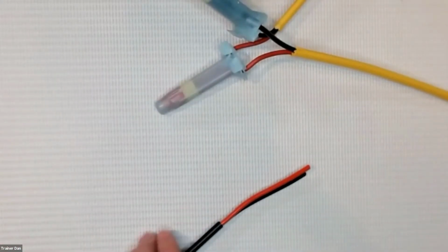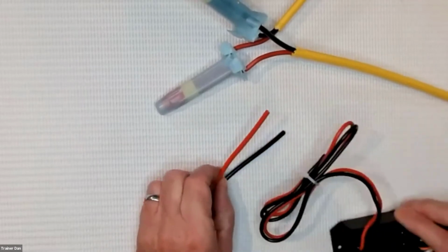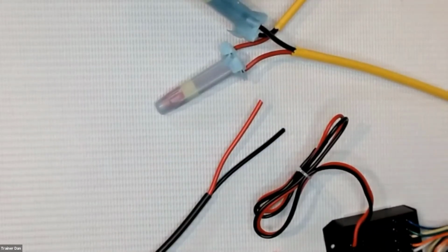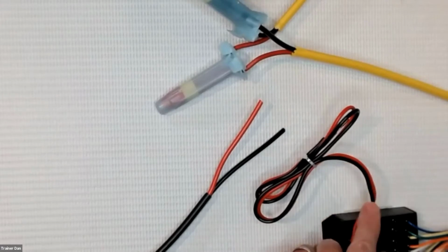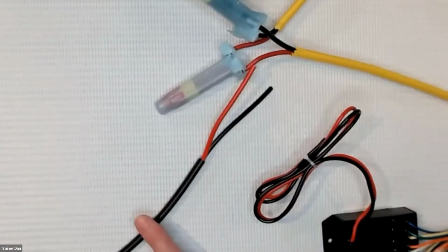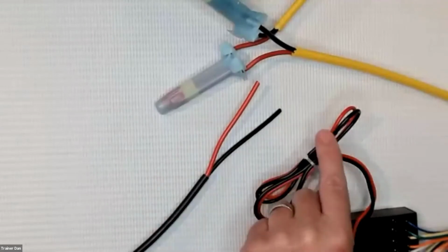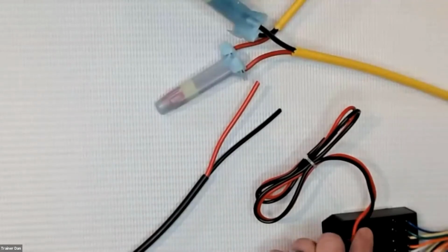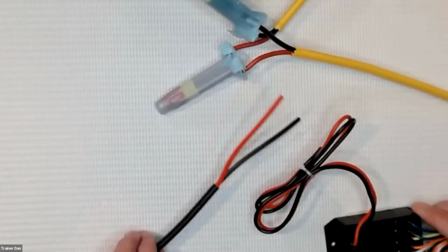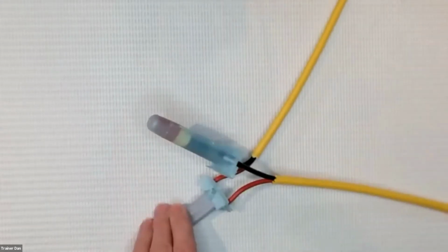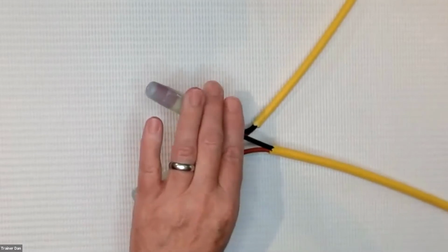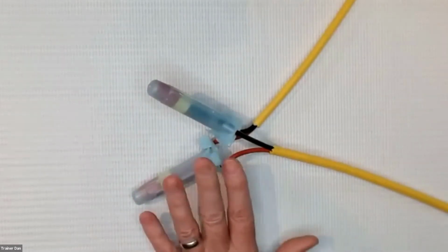Okay, so the device is then going to splice into that two-wire path somewhere along in here. This part of the device is still part of the two-wire path. So we've got the wire itself, the splice, and then up to the device. That's all still considered the two-wire path. There are a couple of things that can happen here, and generally, poor wire path integrity is going to create problems for you.